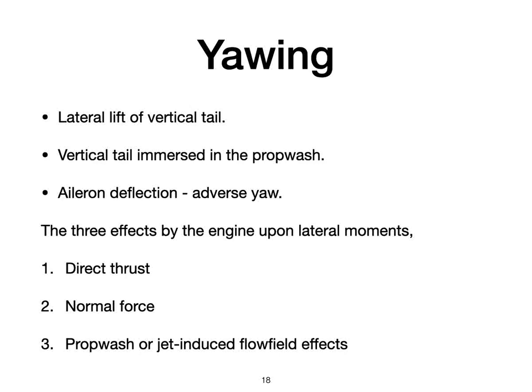Third one, prop wash or jet induced flow field effects. The prop wash or jet induced flow field effects are generally negligible in yaw unless the vertical tail is in the prop wash or near to the jet exhaust.